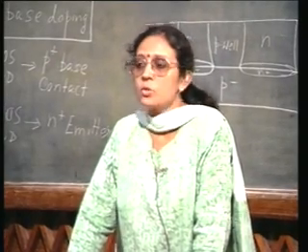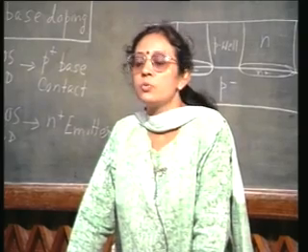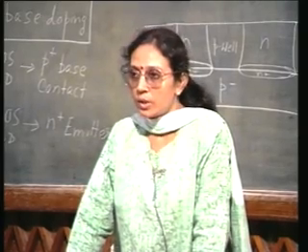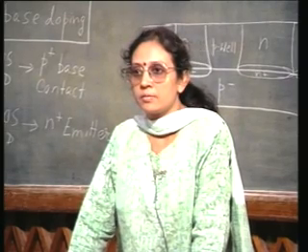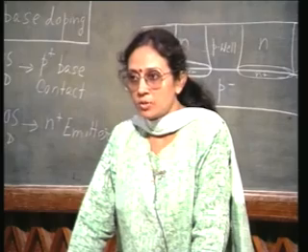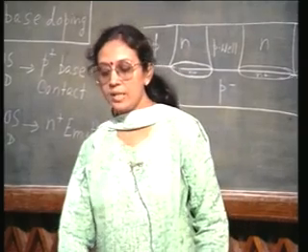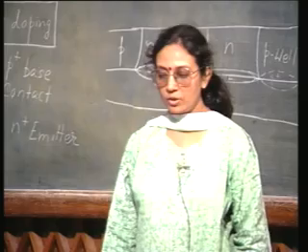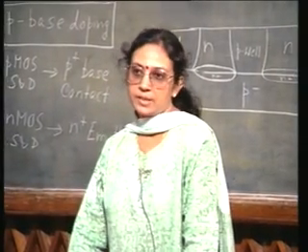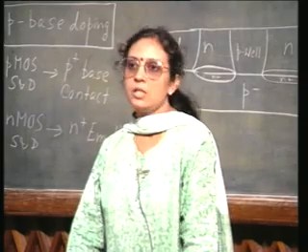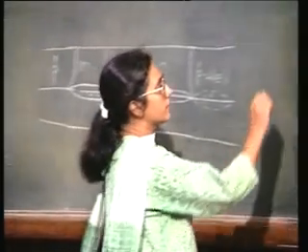So, what do we use? We use, on top of the polysilicon, silicided gate. The same thing we could also use to take the emitter contacts, right? So, the silicided gate can be used as the emitter contacts. Then comes other finer aspects, for example, the LDD structure.